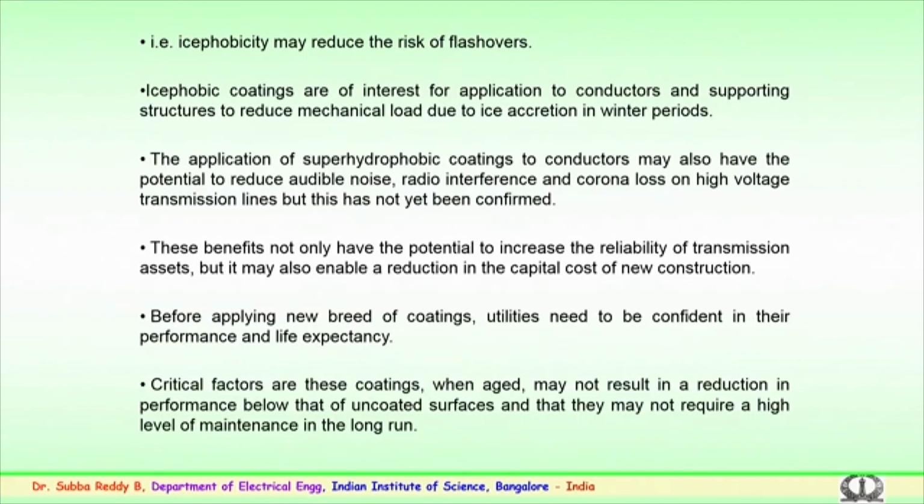So, the application of super hydrophobic coatings to conductors in particular may also have a better potential to reduce the noise, that is basically the electrical noise, what we call audible noise, because of the transmission conductors or transmission hardware, or due to the corona control rings or any other hardware which is in the transmission network.